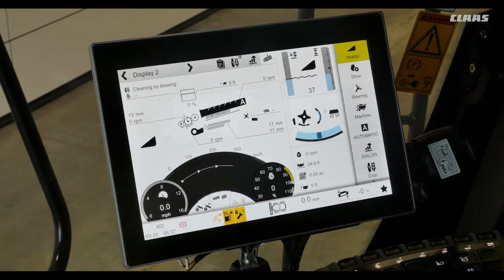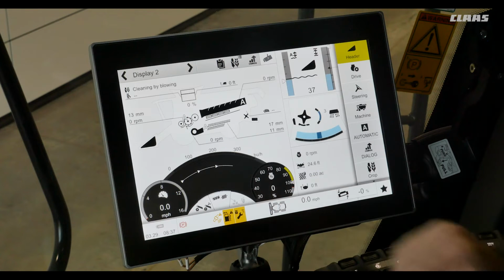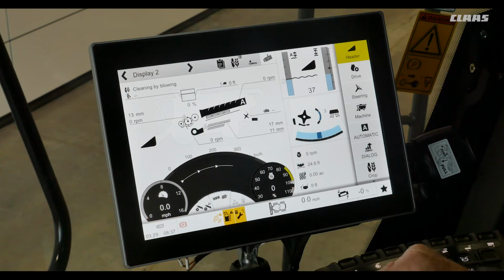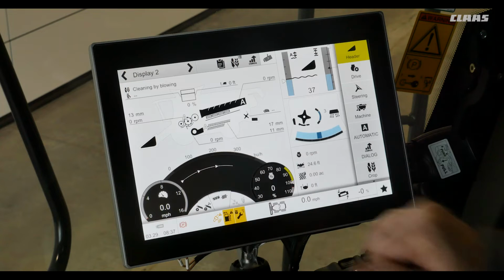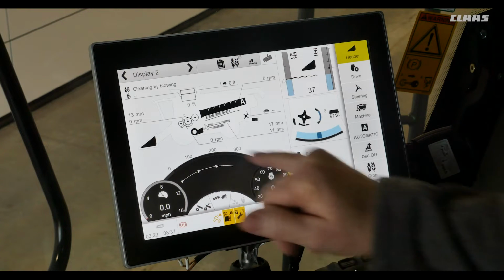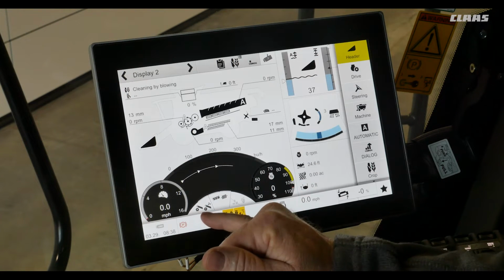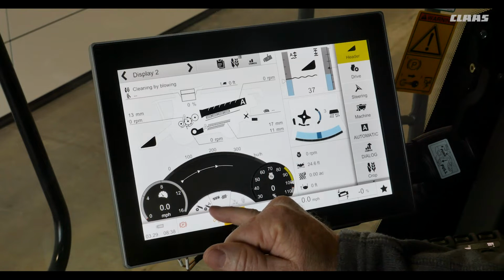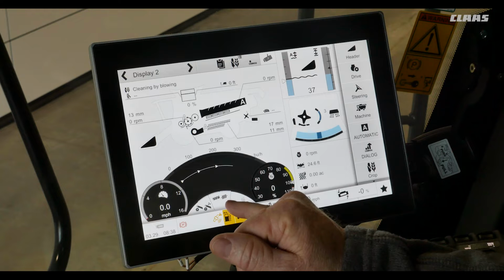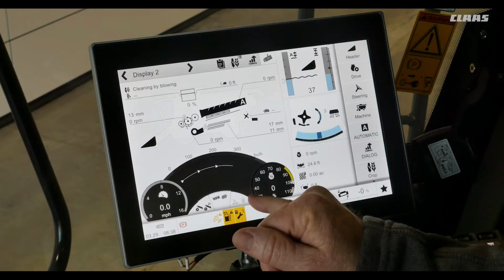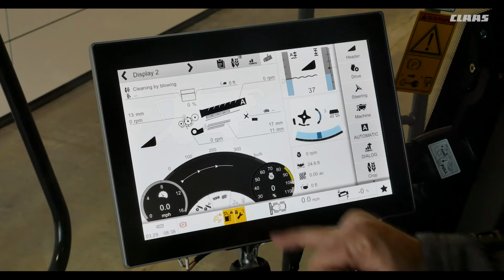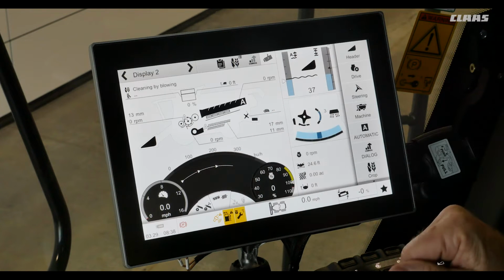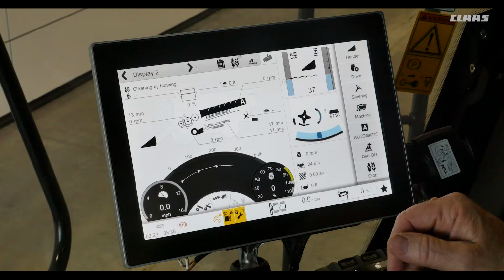Down here you can see our engine load, our miles an hour, bushels per hour on the upper portion of this display. Right here we've got our returns, our grain in the returns, rotor losses, and sieve losses. And if you have auto threshing, you'll have 2 extra displays here. These work coming from the bottom upwards towards the top of this display. So let's get in and do some adjustments.